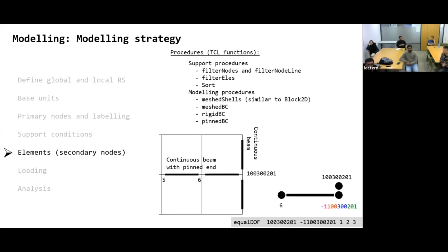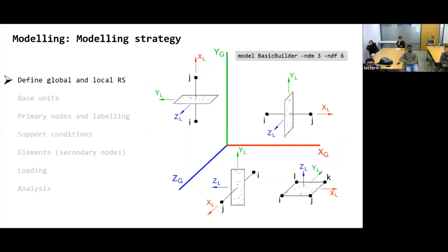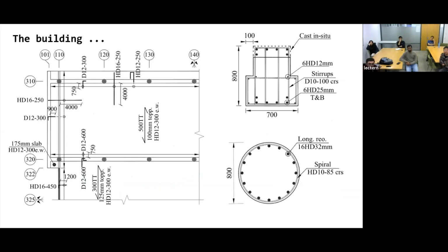This is a pretty interesting case because as we saw at the beginning with the way the building is seated, the double T's are seated there, but they are not continuous. So actually they have a pin connection there. It cannot transfer moment in M3 moment.